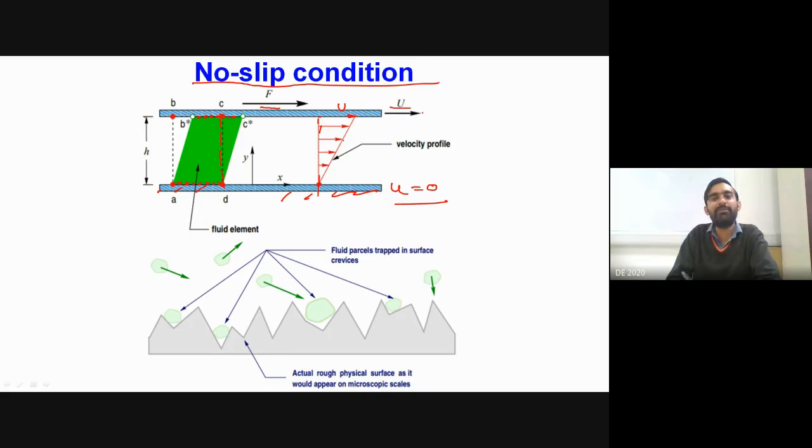And in between, because of the viscosity of the fluid, we will have changing values of velocity between 0 and u. Okay, and we will have the development of a velocity profile, and this velocity profile shown over here we will get once the flow reaches the fully developed flow situation.